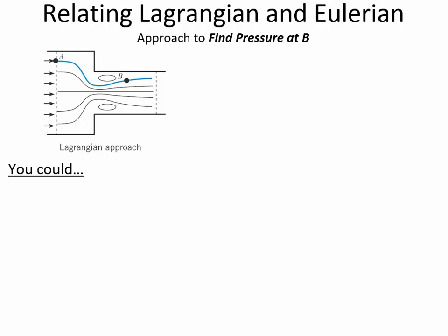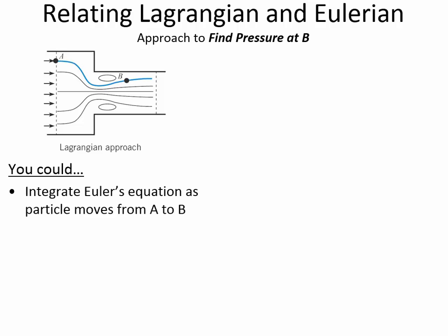So what does that tell you? What equation is probably going to be applied here? When was that an important consideration of ours? Bernoulli, right. Remember, the assumptions behind Bernoulli's equation was we apply it along a streamline for an inviscid fluid, meaning a fluid with no viscosity, an incompressible fluid, and for steady flow. So here we see that Bernoulli's equation comes from integrating Euler's between 2 points.